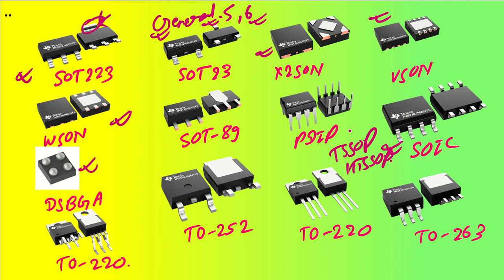Now coming to very high current regulators, let's say 1 ampere, 2 ampere, 3 ampere, all those things. For that, you definitely go ahead with a TO220 or TO252 package. TO220, as I already told you, is a 3-pin package, and there are 5-pin or 7-pin versions. This is TO263, that is the DDPAK package. So these big packages are going to help you with good thermal heat dissipation.